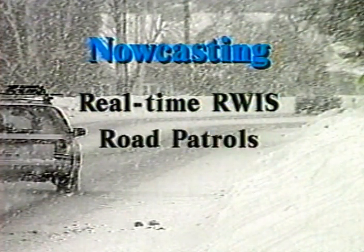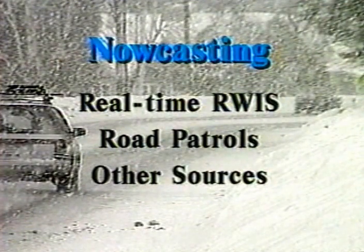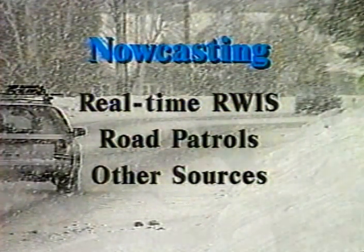The maintenance manager can use nowcasting to decide when to mobilize personnel and take other actions throughout the storm. Nowcasting uses real-time data from road weather information systems, road patrols, and any other sources to predict the weather and road conditions for the next 1 to 2 hours.